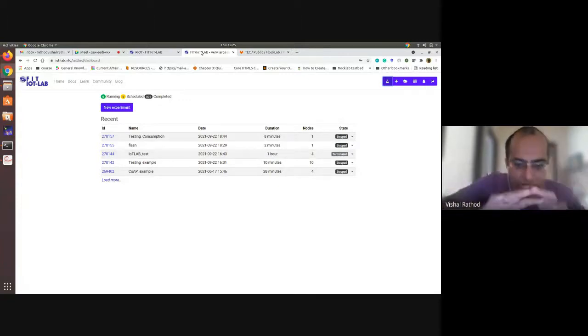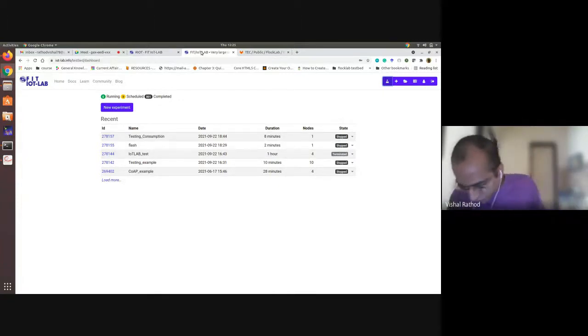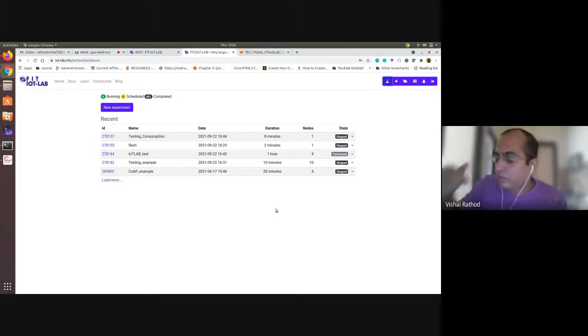What we actually did is we are using a Python client, a Python CoAP client, to send the request to the server through the border router. The border router is used to open the bridge between the client and server, so we can send the request to the server and get the reply from the server.